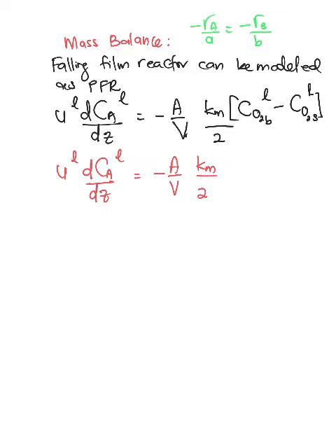Multiply with the concentration of oxygen in bulk fluid. Because the concentration gradient is negligible, it means the change of concentration at the surface of the catalyst is not much. That's why it can be negligible. Right, so this is your overall mass balance equation.